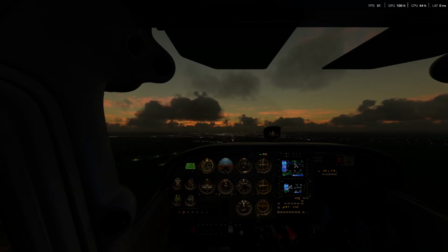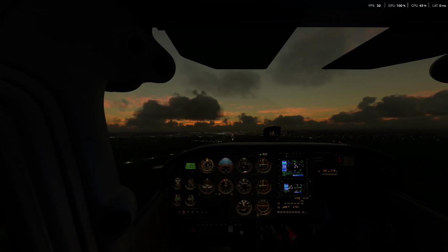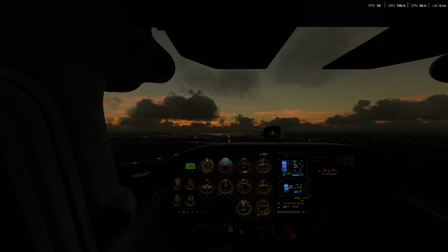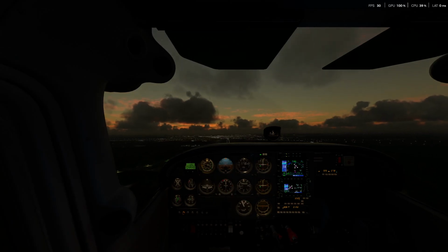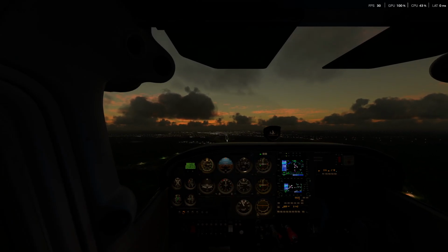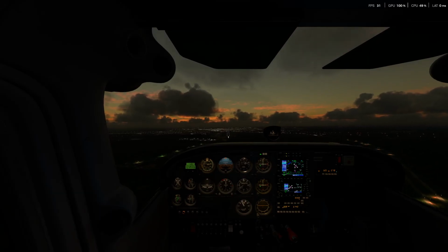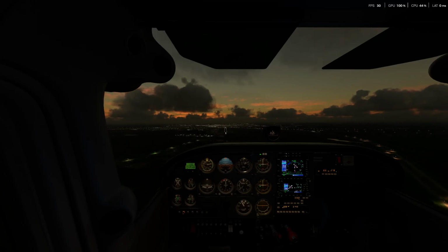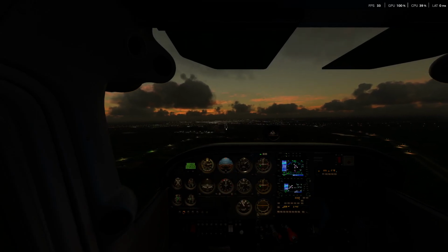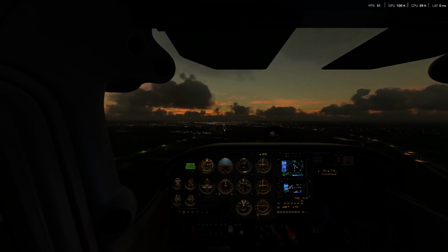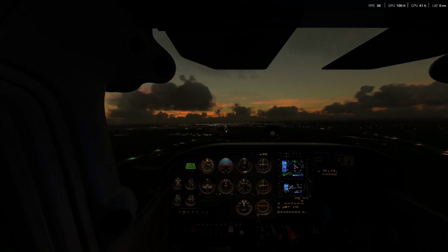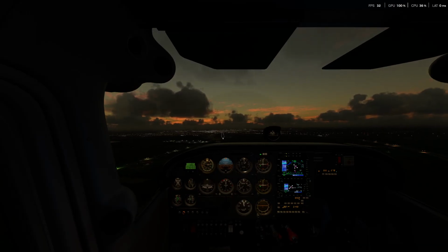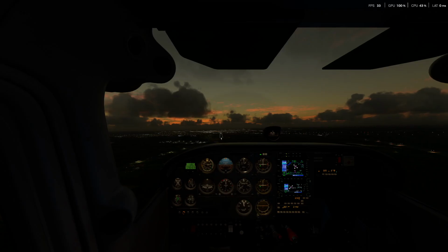Keep raising the nose as the airspeed comes off. Under 110, flaps and airspeed check. And under 85, speed check, flaps 20. Pitch for about 70 knots there, pretty decent. Down just a little bit. So we'll use the attitude for the airspeed, pitch for about 70 knots, and improve on from there. And I'll use the RPM to maintain descent, which is about 500 feet.